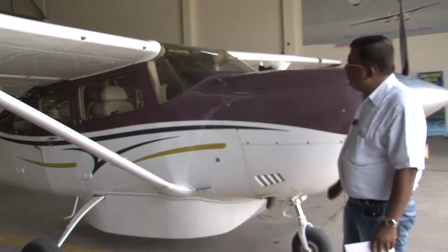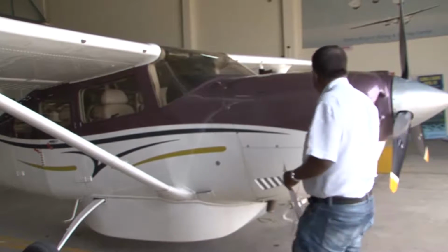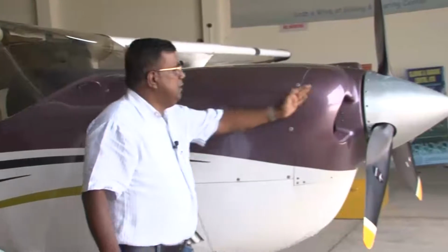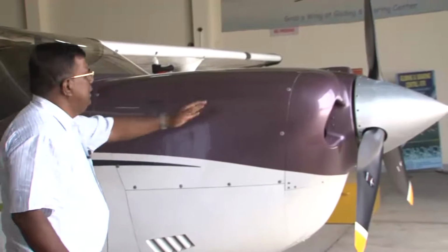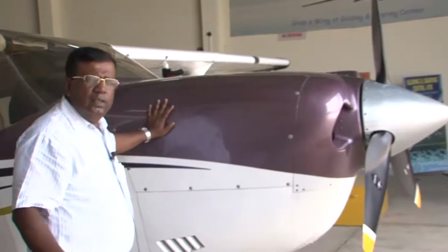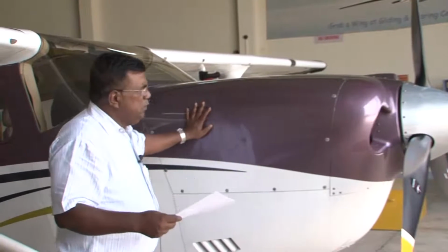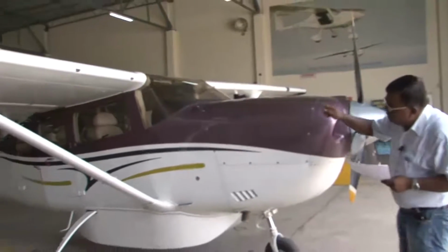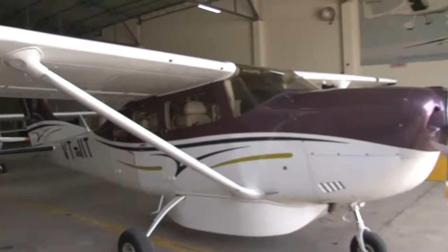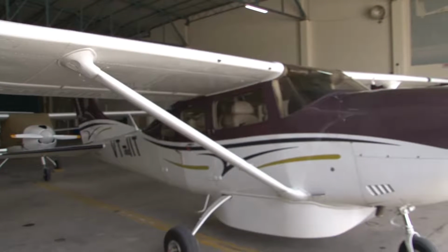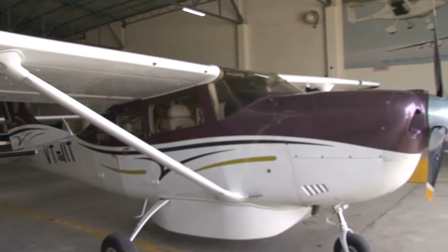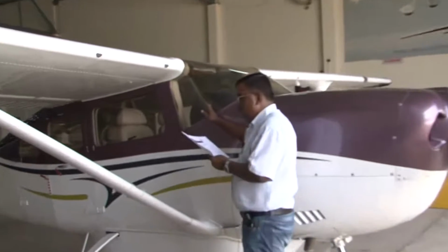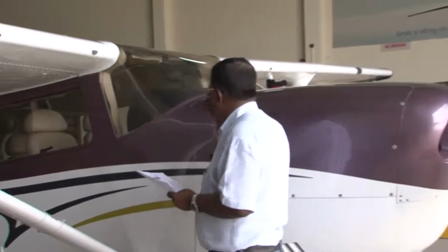So the first thing that should come to our mind is, okay, this is my propeller, then how much distance from here to the cockpit I should keep in relation to the total length of the airplane, generally for a general aviation aircraft. Just to take an example, the total length of this airplane from here to the extreme, that is the tip of the rudder, is around 28 feet 3 inches. How much? 28 feet 3 inches. And from here to the cockpit, it is roughly 3 feet 9 inches.